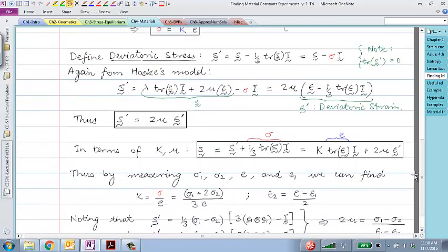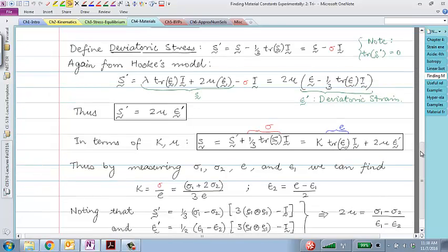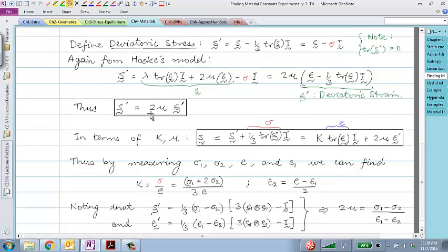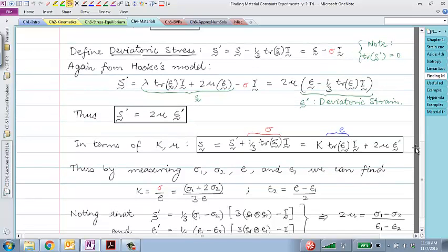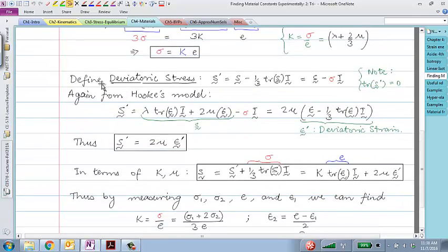There are these pairs of material properties that we are talking about. The first pair was the Lamé parameters, lambda and mu: two parameters to define a linear isotropic hyperelastic material model. Then, with the uniaxial test, we defined Young's modulus and Poisson's ratio. That's another pair of material properties. In the same way, for the triaxial test, people often talk about mu, which is the same as the shear modulus, G, that some of you might be used to. And this is the way that we define the shear modulus.